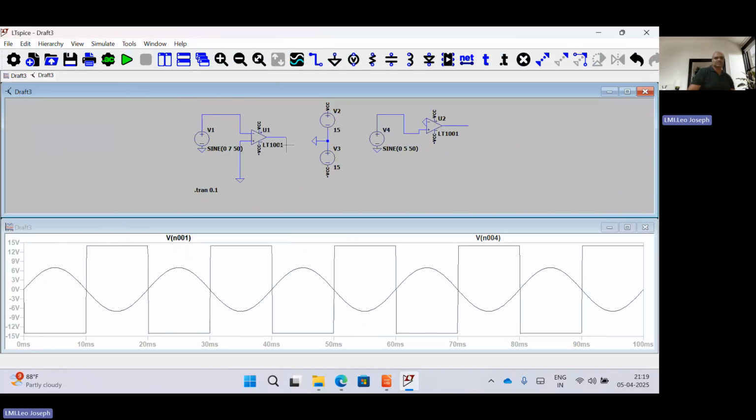If I am only telling this concept, you cannot understand clearly. That's why we are going for this realization. Based on this comparison, the voltage waveform will change from -V saturation to +V saturation whenever it crosses 0. So when it is positive, it will be -V saturation. When it is negative, it will be +V saturation. Like that it will be changing.